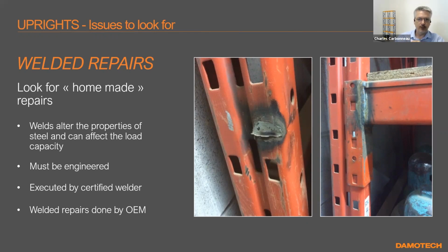They really don't know what to do with this, other than taking an X-ray or taking the beam out and testing it, crushing it basically, and then telling you, oh, it was okay, you were fine, but now it's destroyed. So these welds, you can repair with welds, but they got to be engineered, executed by a certified welder, or they can be done by the original equipment manufacturer. So he would probably do that in their shop and then send you the materials, and it wouldn't look like this.